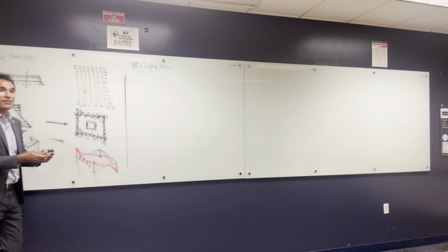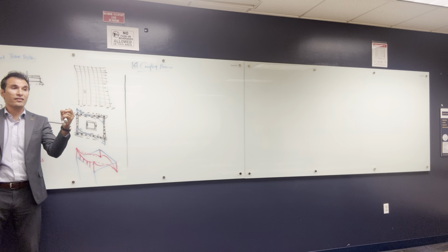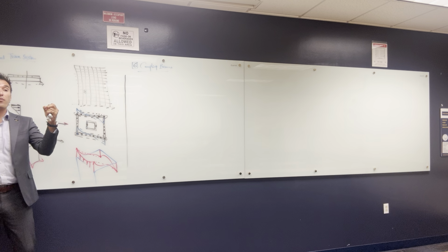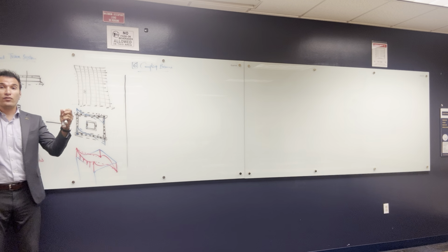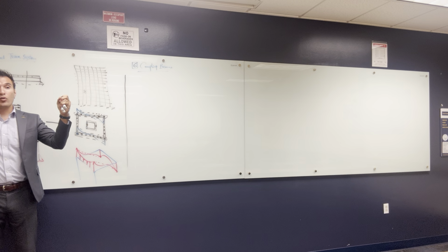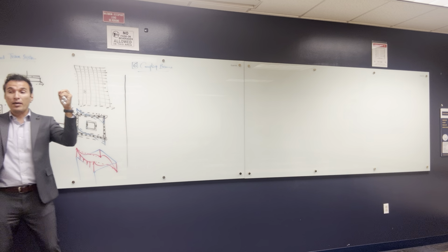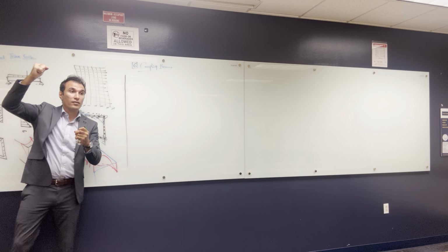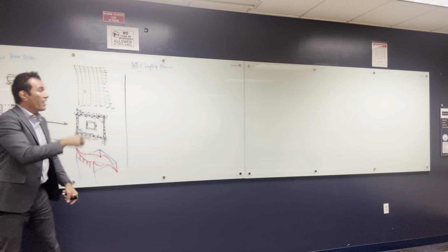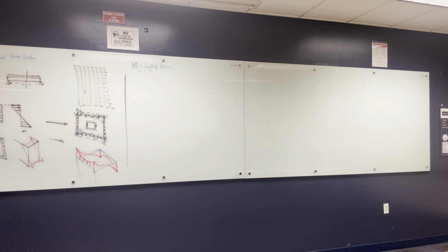What we do in the tube system, we want the two columns to work together so that they can have better bending moment. Rather than each having bending moment separately, you are going to use the force here and the force here with the distance between them to create a big arm of moment to resist the external forces. And that's what happens when we talk about coupling beams.